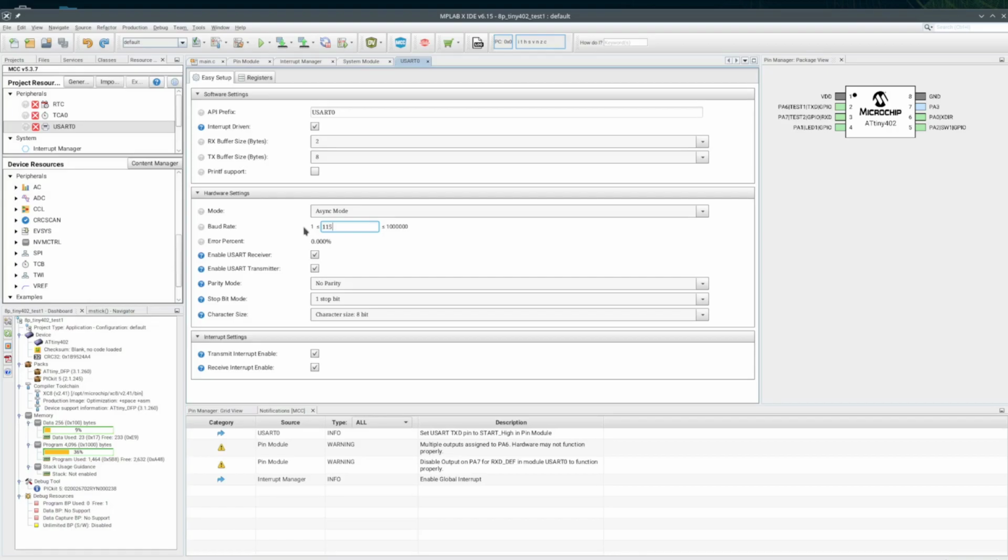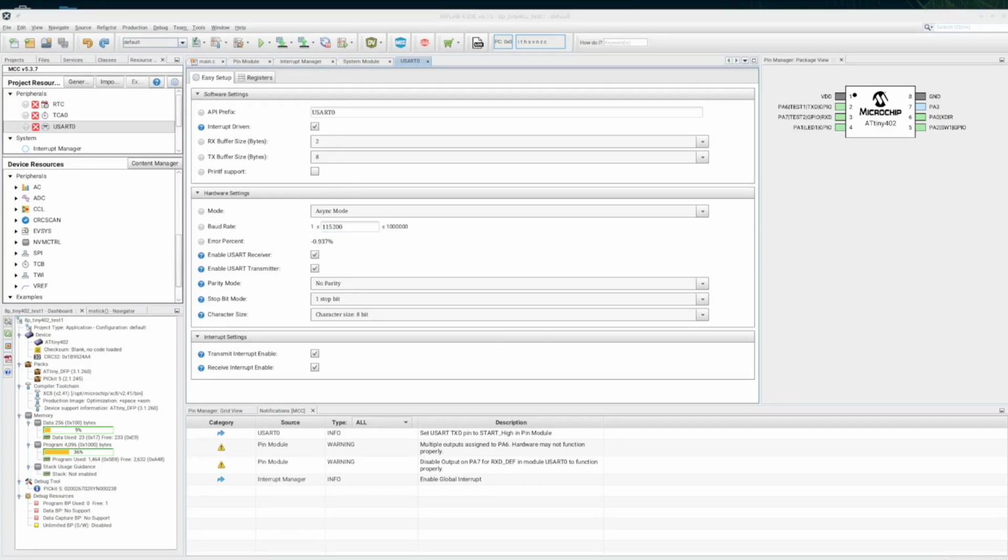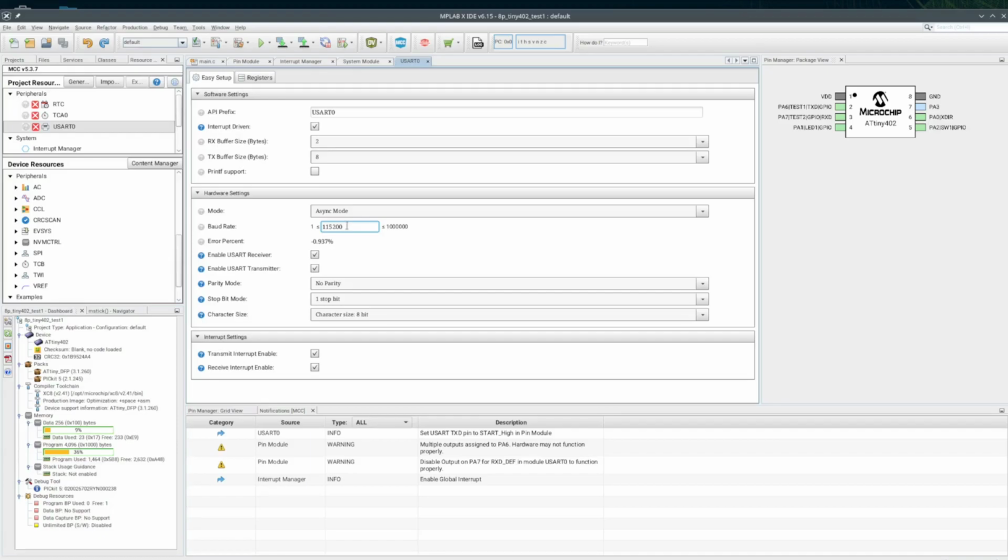I normally default to 115,200 for the baud rate, but with a 2.5 MHz clock, that is a bit more error than I would like. Next step down. That's still a bit more than I would like. Would probably work fine. Okay, 38,400 is less than 0.2% off. That plus the internal oscillator should put me at less than 2.5% off of the 38,400 baud rate. Shouldn't have any problem with that.